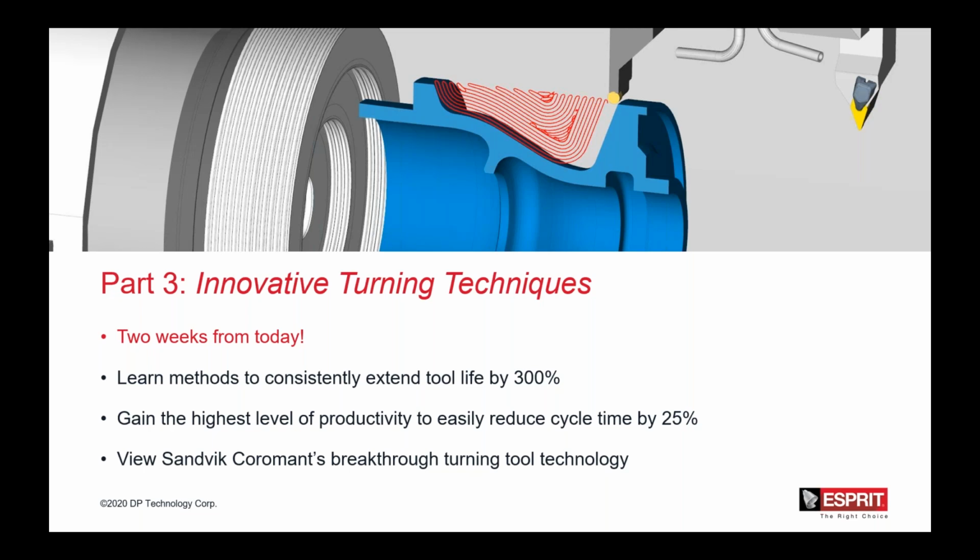So Stephen had another question for Sandvik on the deep hole drilling. When drilling through a part, should a parameter be adjusted for the pressure drop? I'll let Jim take that one. Well, I'm assuming he's referring to the coolant pressure. Yeah, so it sounds like at the end of a deep hole drilling cycle, right before you drill through a part, should you drop the pressure down?